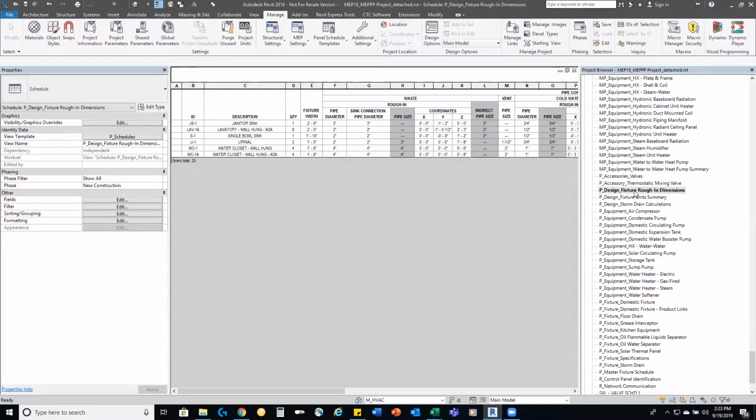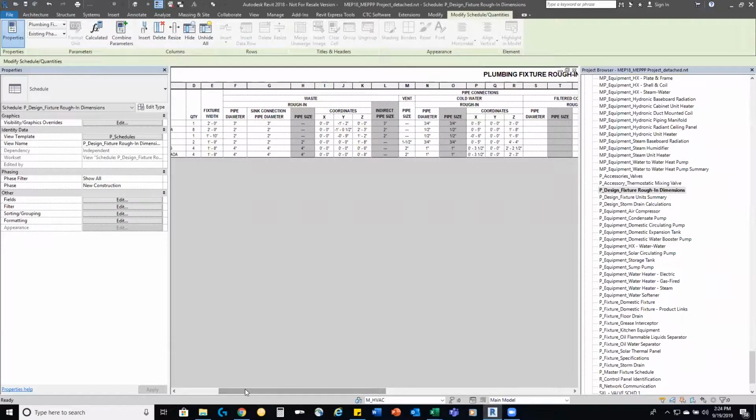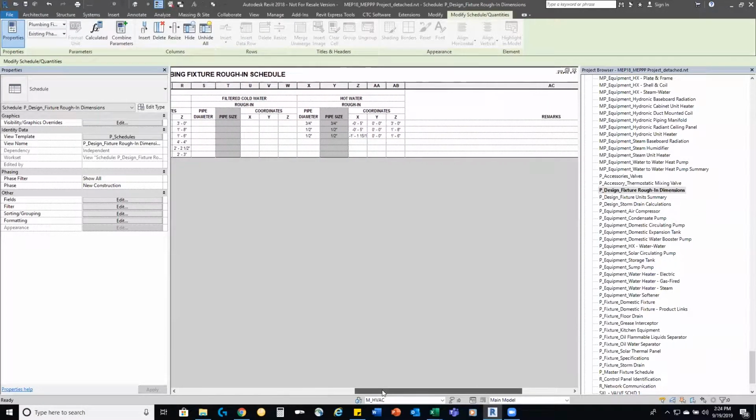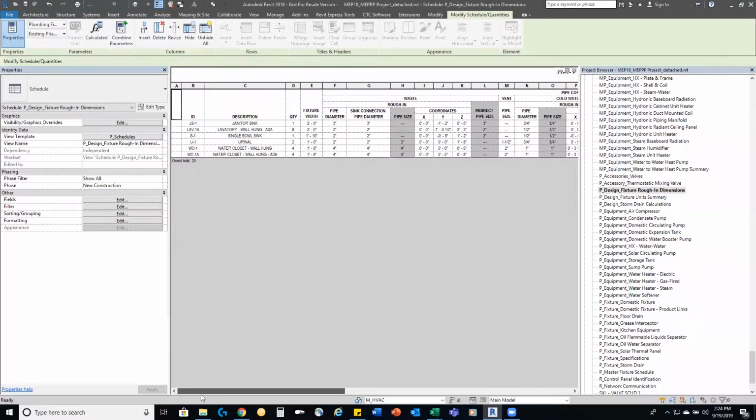And so what we're looking at here is the settings that move the hockey pucks inside of that plumbing fixture around to match your, say, for example, a bowl flush valve combination or a lab with a trim kit, right? We wanted to make sure that we made those hockey puck families flexible enough that you could simply input XYZ values and move those hockey pucks around to match those connecting locations. But we gave you a schedule so that you can do this in a more centralized manner, again, like filling out an Excel sheet, versus going around to every instance in the model, clicking on it and making a change.